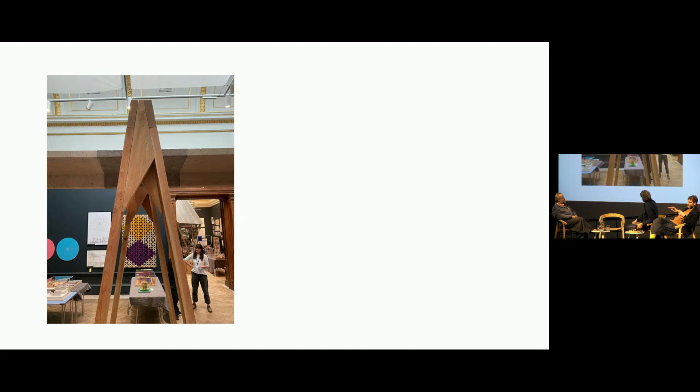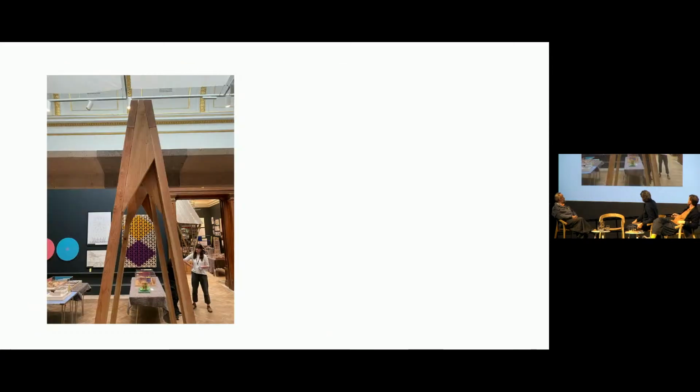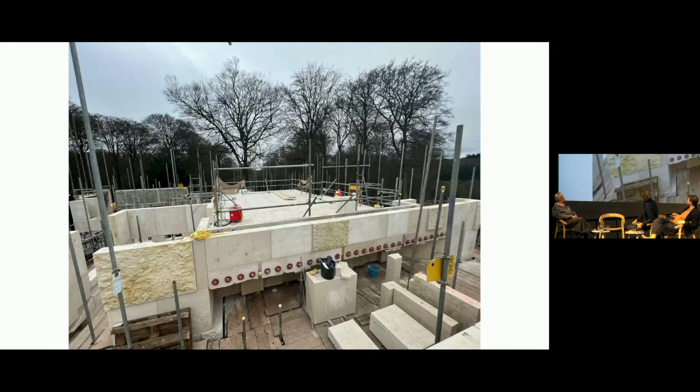Well, we wanted to have a 5.5 meter cantilever, and we thought, what could we fix that to? And the most logical answer, another 5.5 meter cantilever. And then we were worried, actually, that if somebody got on the end here and started hanging, they would pull the whole thing over. So it freely tilts. So if somebody grabbed it, it would just seesaw back and forth. So it's a kind of flexible thing. We won the architecture prize for that.